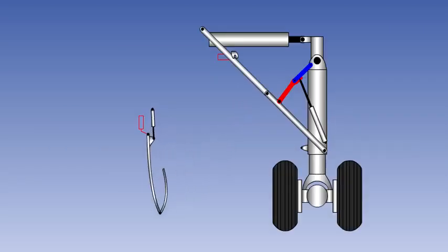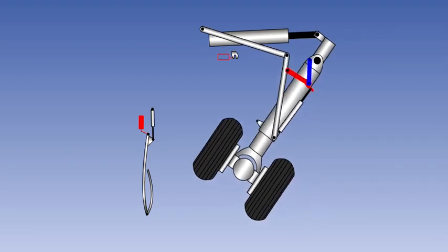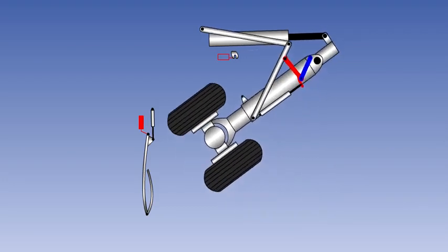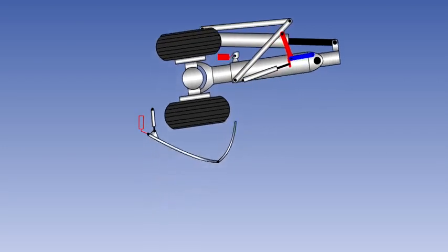On many aircraft, the retractable landing gear is behind flush-fitting doors when it is retracted. For aerodynamic reasons, some of these doors are also closed when the gear is extended. It is important that the correct sequence of door opening and closing happens when the gear is raised or lowered. Sequence valves are fitted in the landing gear hydraulic circuit to ensure this.